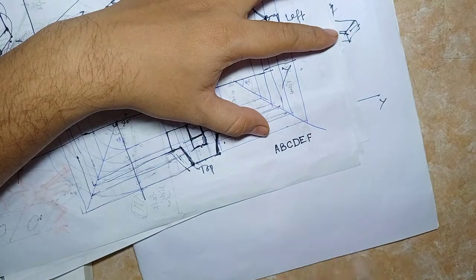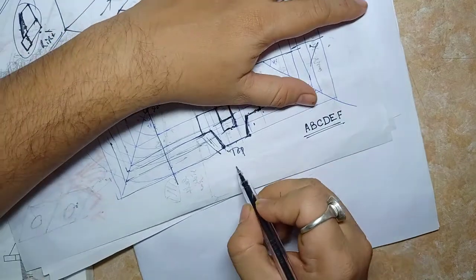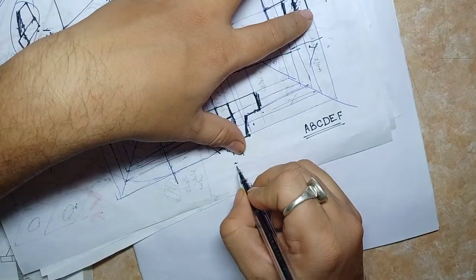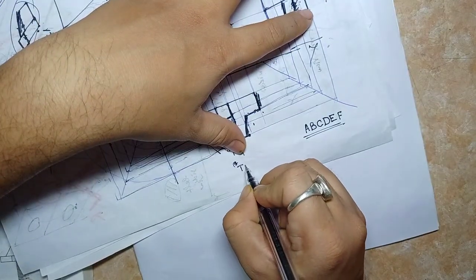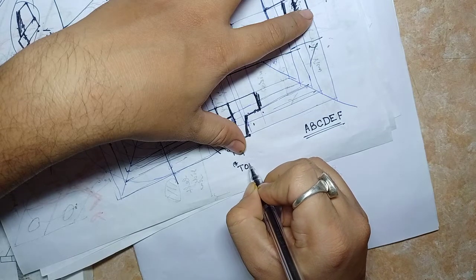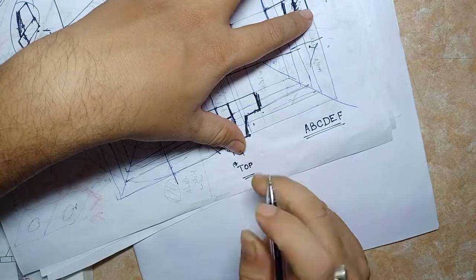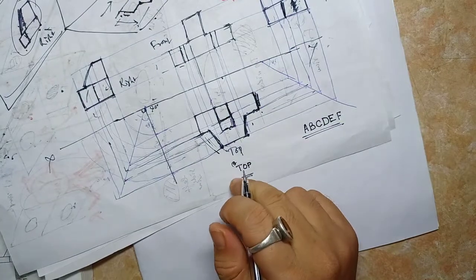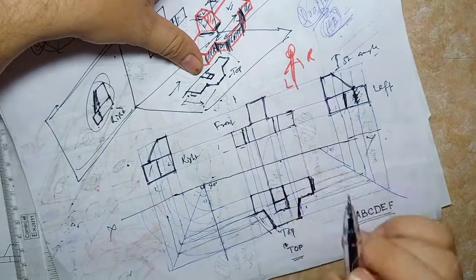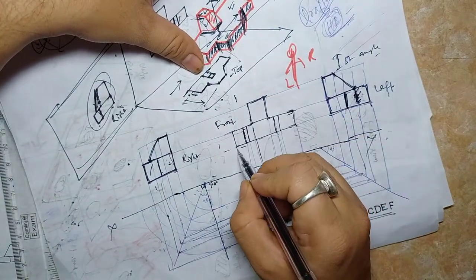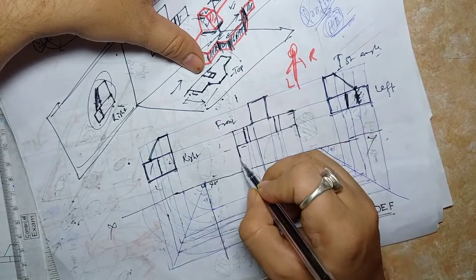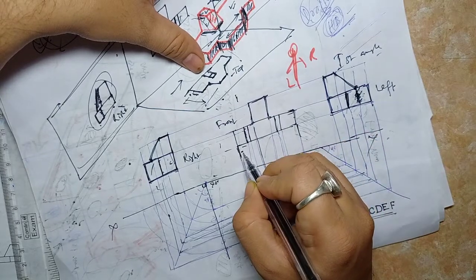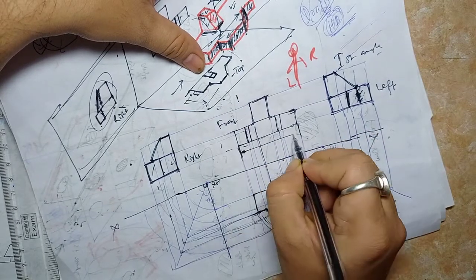Then here, always write top, front view, whatever you write, using engineering lettering. Use this engineering lettering here. And the dimensioning also, you should follow the rules. If you are showing a dimension here, you show it using an arrow. Exactly, the arrow should be